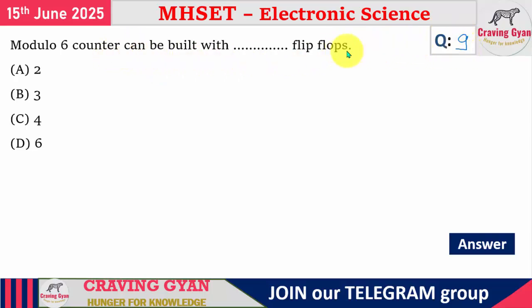For the 9th question, what they have given is a modulo 6 counter can be built with the help of dash flip-flops. Modulo 6 means what? It can count 6 possible states. So with the help of 2 flip-flops, if I am making use, maximum how many states you can count? Only 4 states you can count. Right? Let us assume 00, 01, 10, 11. This is the maximum states you can count.